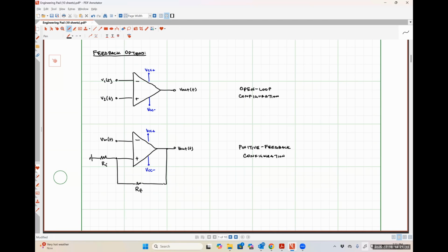Not that this is remotely important to practically any of you, but this particular circuit is what's called a Schmitt trigger. A Schmitt trigger circuit can be used for making analog to digital converters and things like that. It works very similar to how the comparators that I talked about a moment ago work, except that it also has what's called latching. So it kind of holds on to the signal until certain criteria are met.